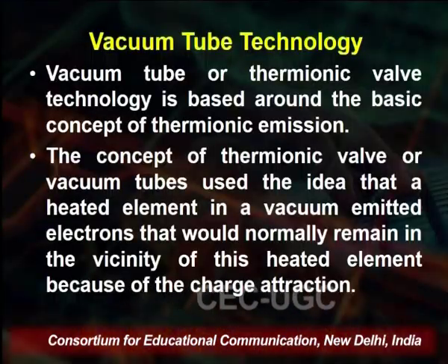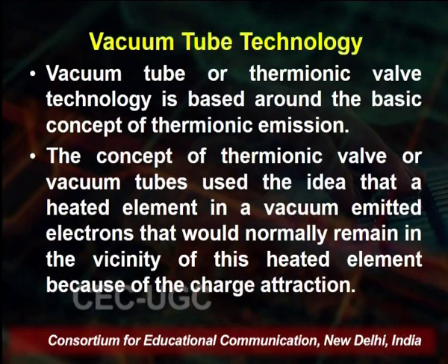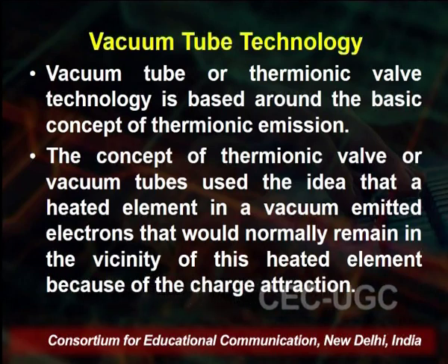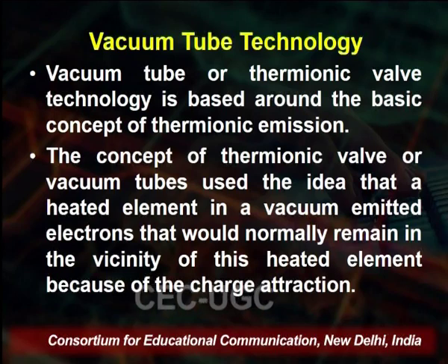So, the vacuum tube technology is not completely obsolete. Nowadays, we also use it. Then, what is the vacuum tube technology? Vacuum tube, or the thermionic valve technology, is based around the basic concept of thermionic emission. The concept uses the idea that a heater element in the vacuum emits electrons that would normally remain in the vicinity of the heated element because of the charge attraction.